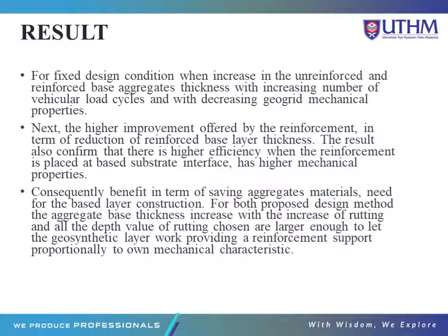Next, the higher improvement offered by the reinforcement is in terms of the reduction of the reinforced base layer thickness. The result also confirmed that there is higher efficiency when the reinforcement placed at the base subgrade interface has higher mechanical properties. Consequently, there is a benefit in terms of saving aggregate materials needed for the base layer construction.